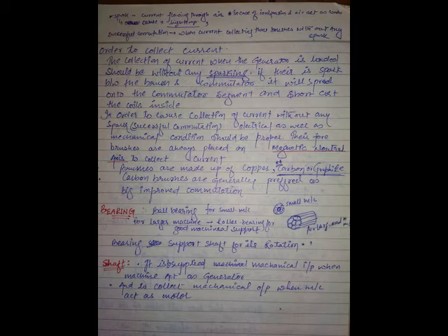So you can take AB as one conductor, CD as the other conductor. You can represent it by Z. Conductors are represented by Z. Let there be Z number of conductors. According to Faraday, they are represented by N actually. Yes or no? E is equal to N d phi by dt. So here we are changing the notation; the standard notation is that conductors are represented by Z. N is taken for speed of rotation, N RPM. So N is represented by Z here, the number of conductors.